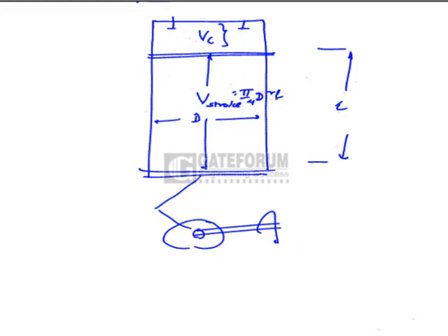The reasons for this decrease of volume are: number one, throttling at the inlet valve. There is a pressure drop across the inlet valve during suction due to the throttling effect, and because the leftover exhaust gases inside are hotter, they also contribute to the decrease in volume of the air or air fuel mixture sucked into the cylinder during the suction stroke.